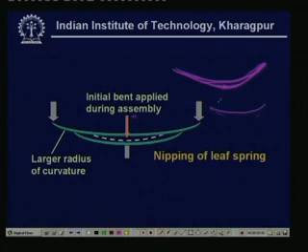Now, if you are bending it by this amount, then what is happening? This is getting stressed, meaning it has more compressive stress, negative, and this has more tensile stress. And what is happening to this one? This one was like this, it had some stresses, and this particular one is trying to flatten out more. That means it will have a tendency of opening out. That means it is going to be more stressed in these directions.